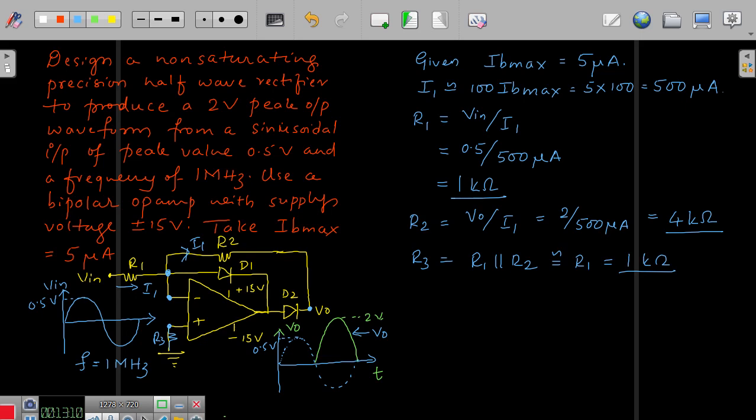That is basically this resistance is used to have the equal voltage drop. So that is basically when there are internal transistors, whatever the bias current you are going to give, the base currents should be equal. In order to make sure that the currents are equal, outside you would like to have the equal potential difference.